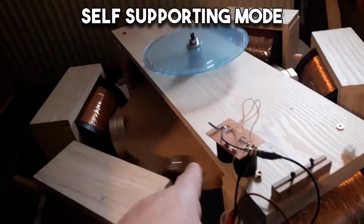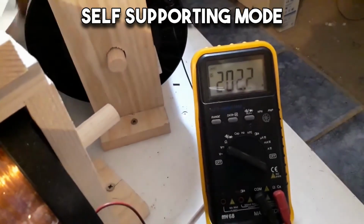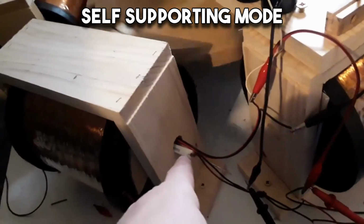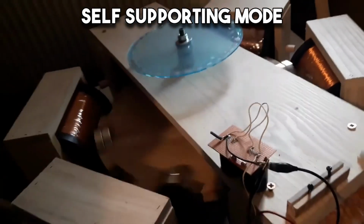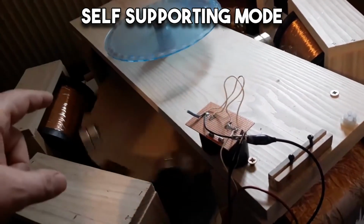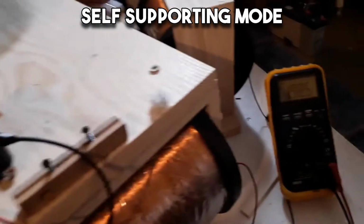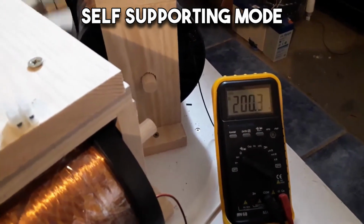I push this rotor by hand and you can see that I'm charging the capacitor. It's climbing up. What I have is a capacitor of about 1 microfarad and reed switches inside of this coil. What I got is that generator mode and motor mode rotate in the same direction. Because I push by hand, now it's a generator and it's charging up the capacitor.